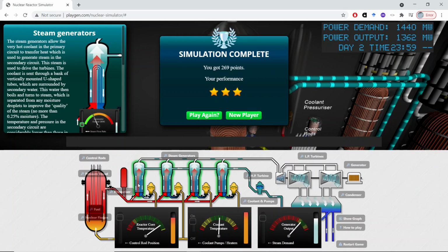And the Russian VVERs, which are also pressurized water reactors with very similar specs to this one, in terms of primary pressure, secondary pressure, power output of around 1000 megawatts, etc., have, I think, 3 and not 4, but I'm not really sure about that, steam generators placed horizontally inside the building, which is quite interesting. And the fuel assemblies are not quadrangular prisms, they are hexagonal, which I guess gives better controllability of the local activity of the reactor.